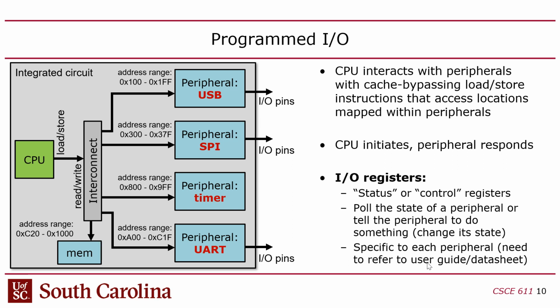Actually, technically you can't even access I/O addresses in a Linux program because you have a virtual address system in your user code. The I/O addresses are physical addresses that exist outside of the virtual memory system, outside of the page table that Linux has, right? So if you have an operating system like Linux, you can do this as long as you write a kernel driver, kernel module.